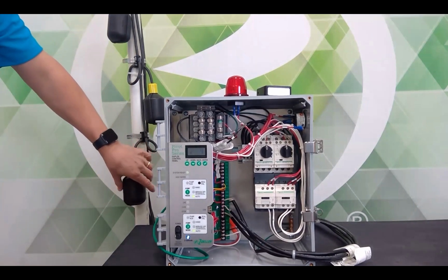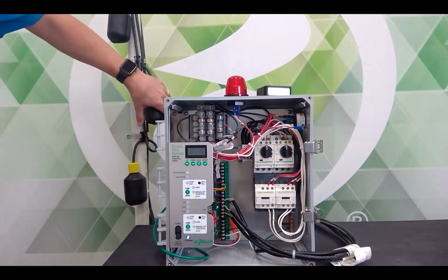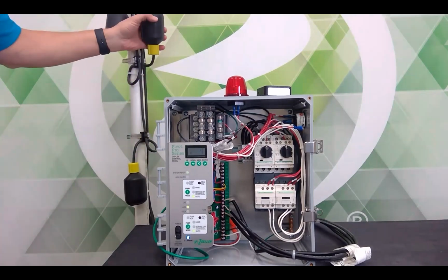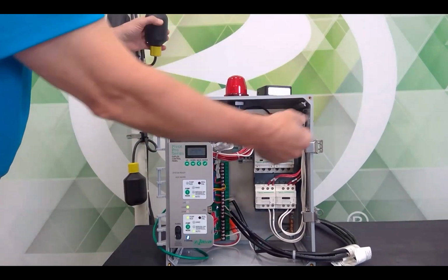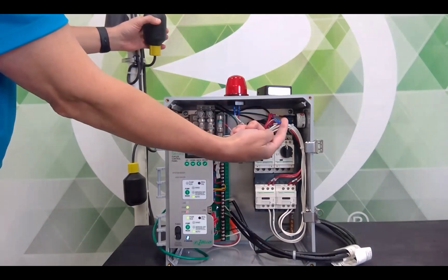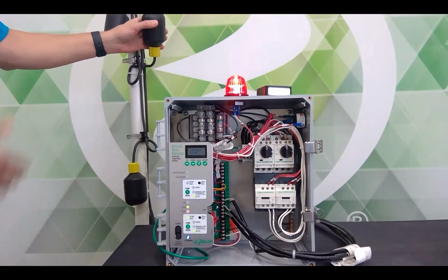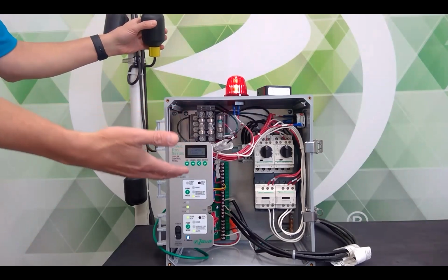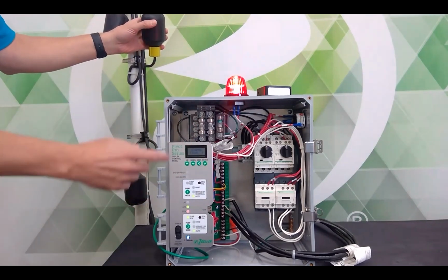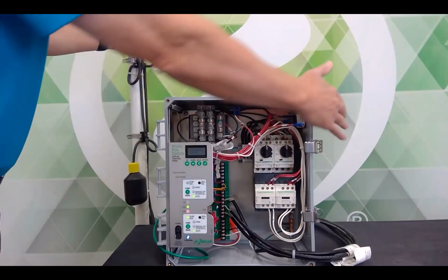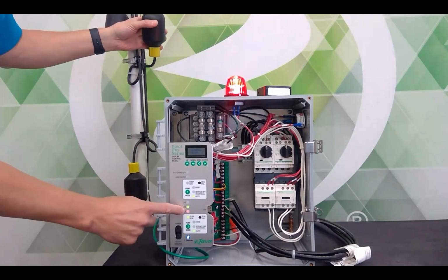All right, so we've got a stop float here. Let's assume that that was stuck and we're only going to lift the lead float. Now, normally the alarm would be going off. I have it unplugged so that you're not suffering. But notice, I don't know if you heard the contactor pull in, but the pump is running right now. Contactor pulls in, runs the pump. I've got an alarm. I've got a horn. I have my stop LED here blinking red.